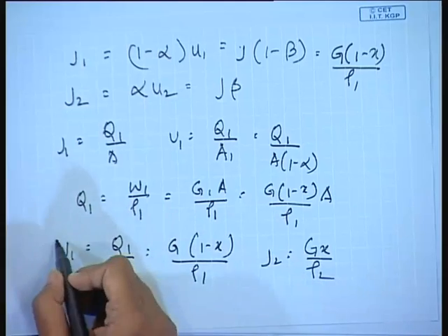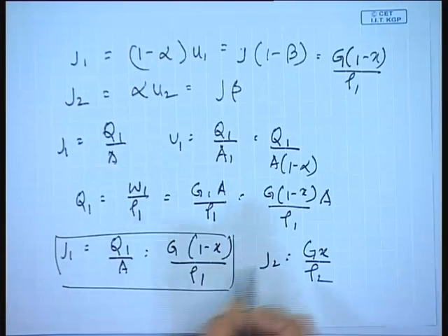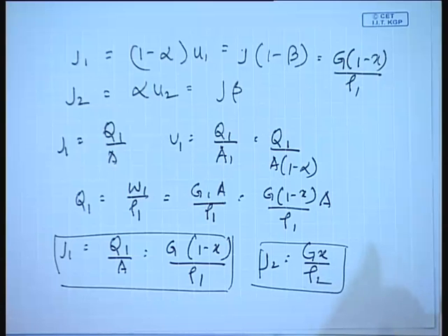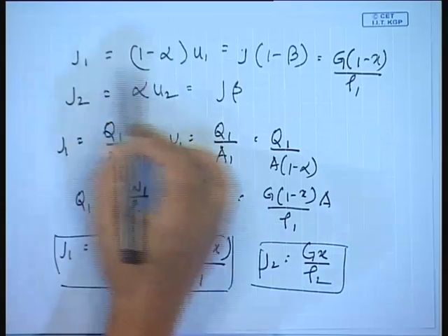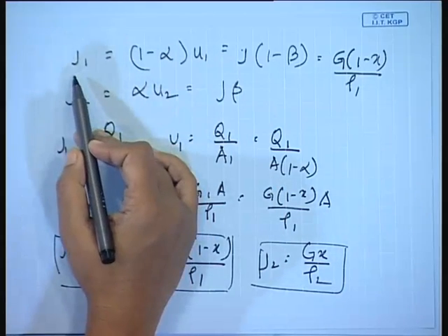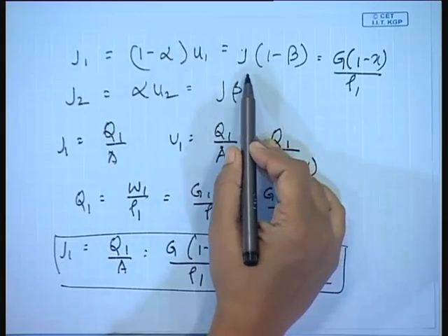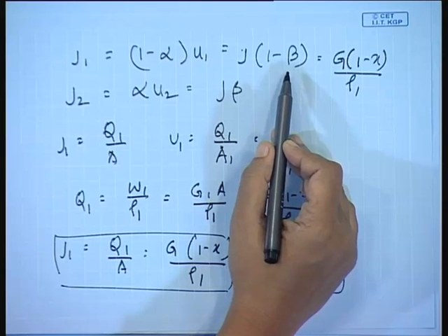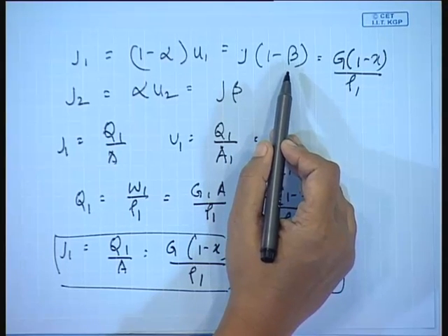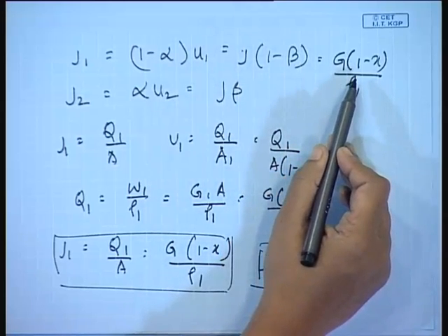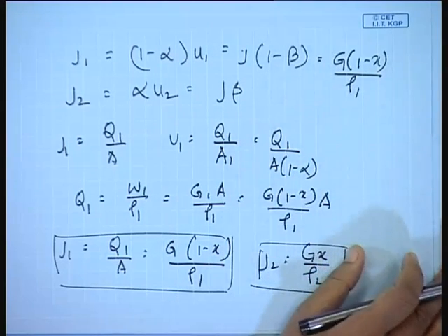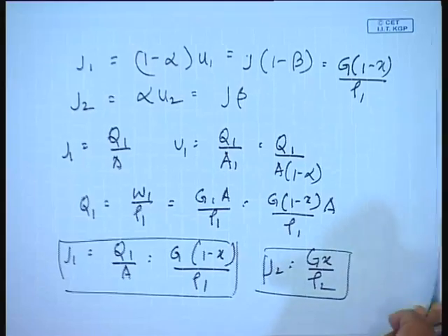Okay. So, this relationship relates the overall mass flux and the component volumetric fluxes. By this relation we have related the volumetric flux with the void fraction, the volumetric flux with the inlet void fraction or the inlet volumetric composition, and the volumetric flux with the total mass flux. Or in other words, with the component fluxes, if you see how the volumetric fluxes and the mass fluxes of individual components are related, that is quite natural.